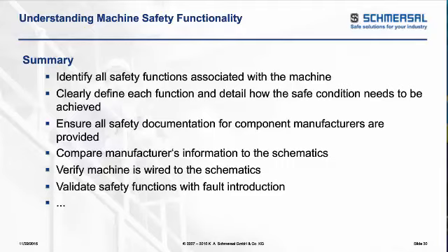You need to have that open line of communication and decide how that safe condition needs to be achieved upon actuating that safety function, whether it be an e-stop, a guard door, muting light curtain, or a 3-position enabling circuit for setup mode. What is the safe state of the machine upon triggering of the safety device? How are you actually achieving it and backing it up?